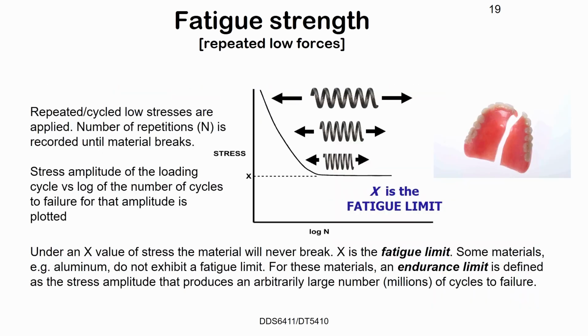So just summarizing what I've said, we can plot the stress amplitude against the number of cycles to failure. And you can see this sort of exponential reduction in the stress amplitude against the number of cycles. Now, at some point, when the stress is so low, you will never get fatigue failure.